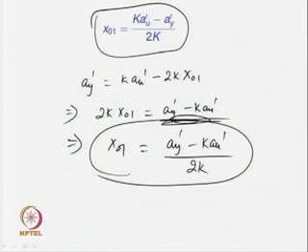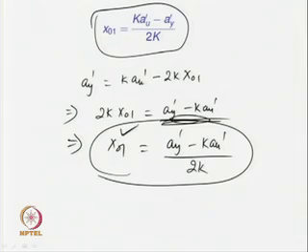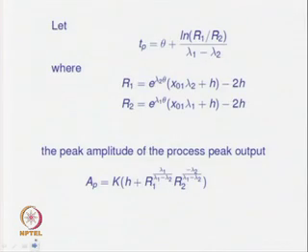When A y dash and A u dash can be obtained from the output signals, then we can estimate x 01 conveniently, and this expression can be used to estimate one parameter associated with the transfer function model. Now, I will go to other expressions which are presented outright. I am not repeating the detailed explanation or the expressions required to find the final expressions, already we have presented